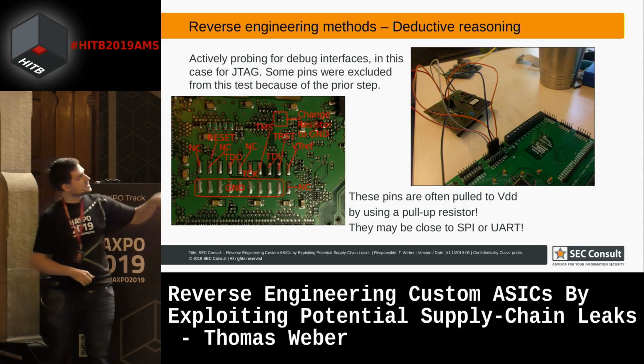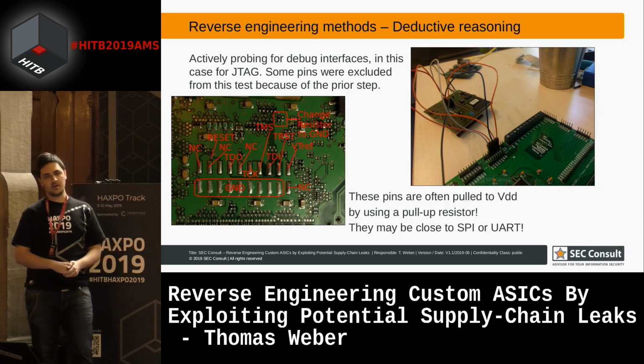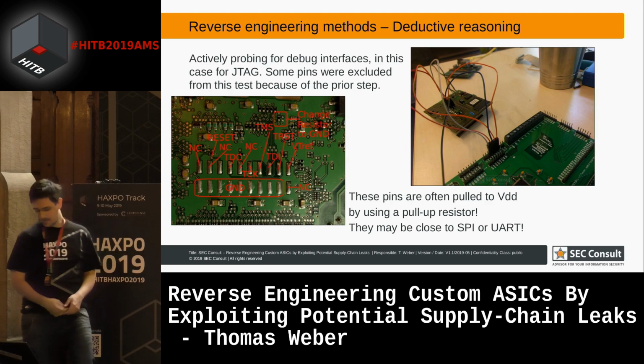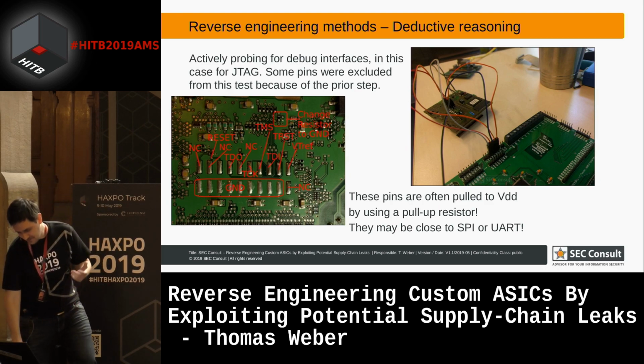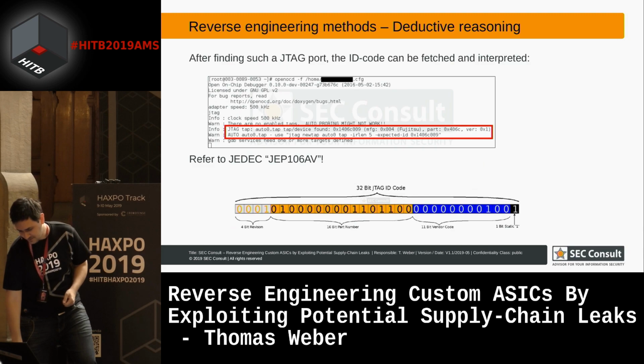And there was some small resistor, which was next to the pins of the debug interface, and I just tried it out, and it worked. So I got access to the debug interface and had all the options which are the same like the options from a developer, and yeah, that was great. But yeah, it was a little bit hard to figure that out.